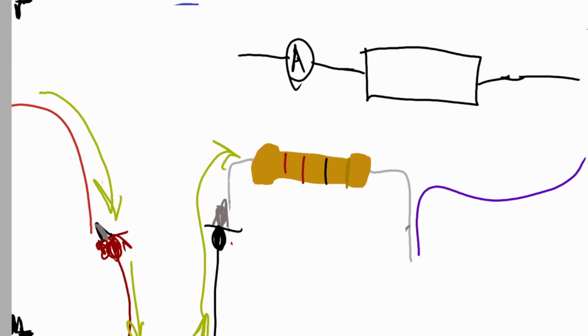It could be the case that you're asked to measure the current this way. Lastly, to measure the resistance, take your component while the circuit is unpowered, and, exactly the same as with the multimeter, measure across the resistor.